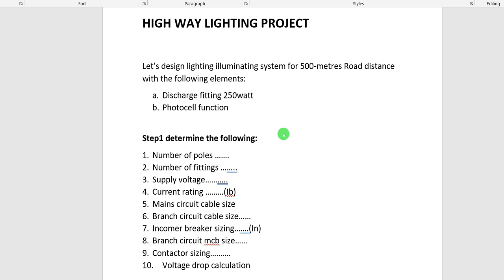The electrical engineer is expected to put that same design into the system and start designing the lighting load, the power load, the cable size, the voltage drop, the MCB rating, transformer sizes, generator sizes, and do the load distribution, the load segregation, and all whatnot. So that is what an electrical engineer would do.